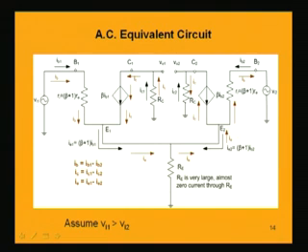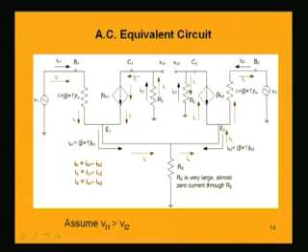So, the input voltage Vi1, then the base terminal of the first transistor Q1, then beta plus 1 into Re is the resistance between base and emitter, which we derived earlier while discussing the transistor model. We are just replacing the transistor with its equivalent model. The first transistor model is this part, Q1 having B1, C1, E1 corresponding to the base, collector and emitter terminals of Q1. Between emitter and base is the resistance Ri, named to denote the input resistance of the transistor, and its value is beta plus 1 Re, which we have derived earlier.